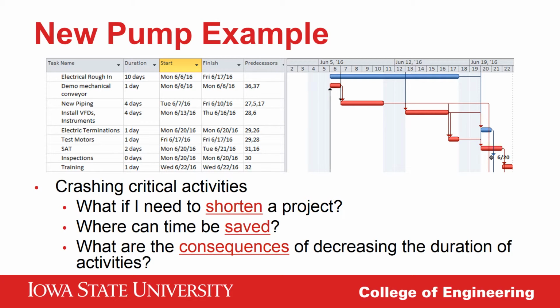If I were in front of you, I'd ask if, due to the nature of the Gantt chart timeline, any of you saw some obvious ways to shorten the downtime. But since this is a recording, I'll tell you that I see weekends. This work is electrical and mechanical in nature. Those types of contractors have multipliers that are pretty effective in modifying costs for weekend or overtime work. They even adjust for productivity losses of each worker when the days are more than 10 hours long.